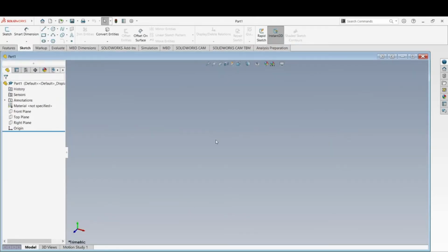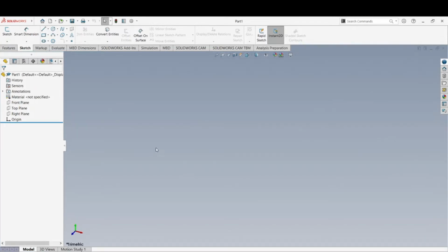A couple of things I noticed working with the guys was this particular SolidWorks is not set up for 3 decimals yet. You can set that as a global template. I can make a video on how that works in the future. But for right now, I'm going to show you how to change the document settings for this part file, in order to make all of your dimensions 3 decimal places instead of 2.